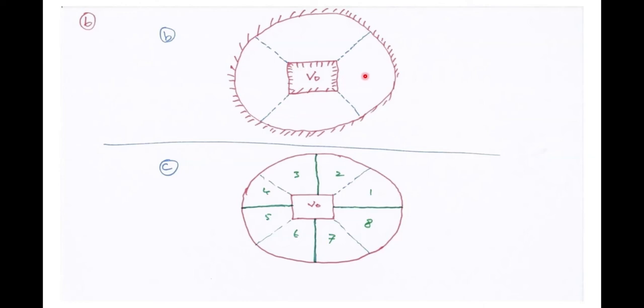We can further divide the space in between the two conducting boundaries into bigger symmetrical flux tubes. So from the mid of each side of the inner conductor, we can draw a streamline which terminates on the outer conducting boundary. In that way, we can include more big symmetrical flux tubes.